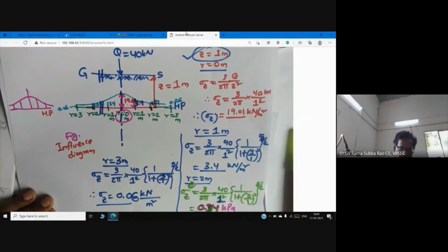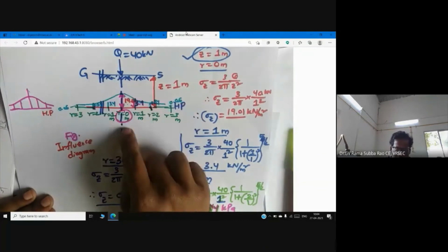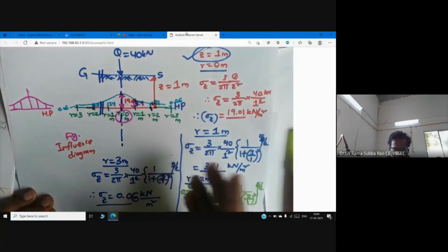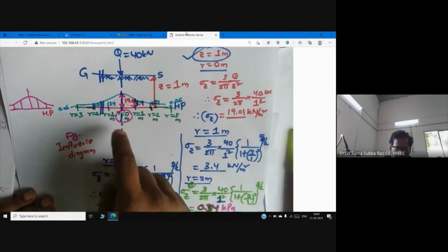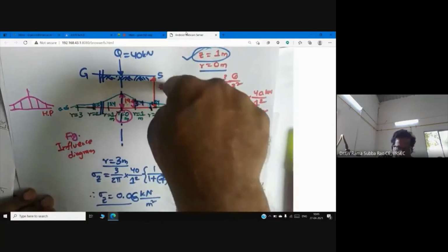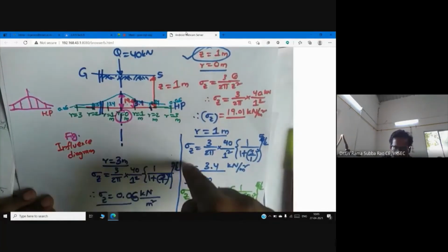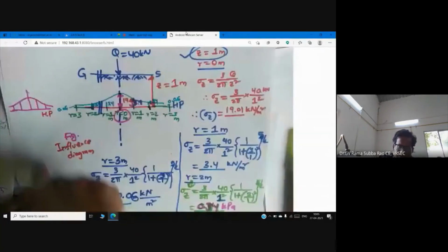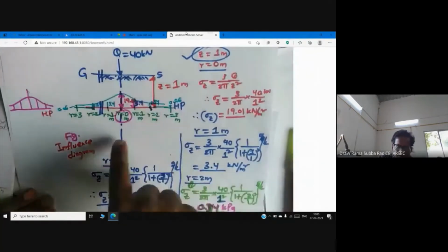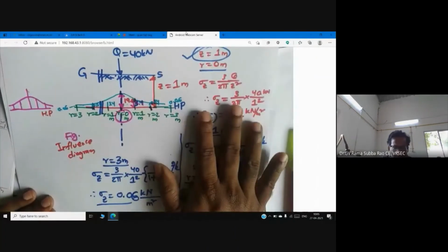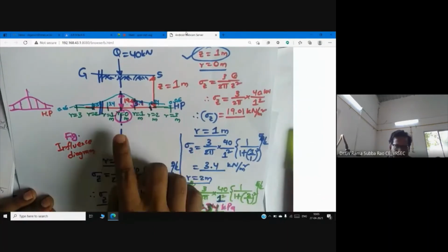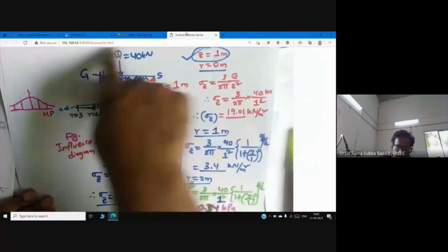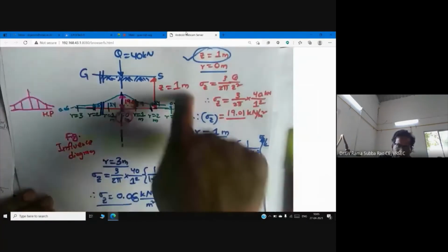What I would like to ask you is, how is the stress varying on the horizontal plane? When you are under the load, when you are far from the load, what is going to happen in all the directions? Because here R is not only the horizontal distance; strictly speaking, R is the radial distance. You understand that R is not just, by seeing an orthographic projection, you would have thought R is just a horizontal distance. So I don't want to accept that. R is the radial distance, so it goes to all the points. Okay, so now tell me.